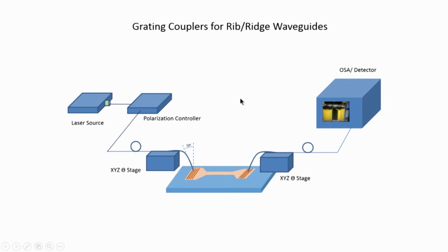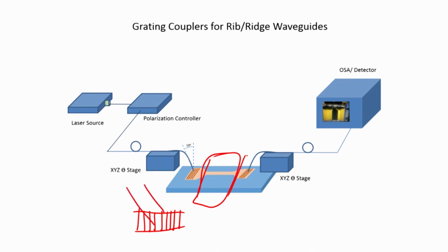So, this is another new process which has become important recently, called the grating couplers. On the same wafer where you have the optical circuit, you create waveguide gratings. Waveguide grating, as we have seen, is a periodic variation of the refractive index, and it is possible to work out when a light is launched from an optical fiber onto the grating. The light could be just coupled into the optical waveguide. So, the light coming from an optical fiber falls on the grating and couples into the photonic integrated circuits.